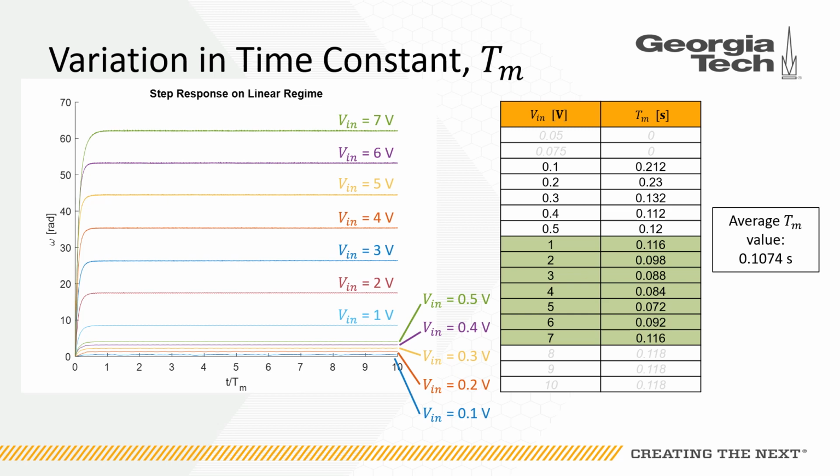Individual values for Km and Tm varied even though they should have theoretically been constants. Since time domain analysis primarily depends on the input voltage for the system, this may be explained by discrepancies between the displayed input voltage and the slightly different voltage actually being passed through the equipment because of internal resistance and signal noise.